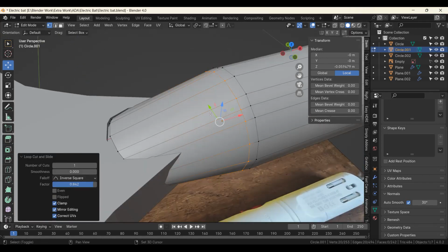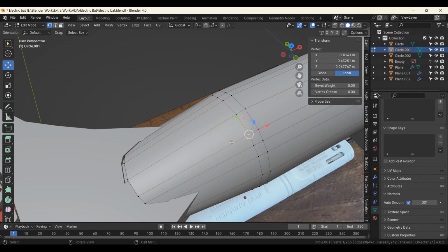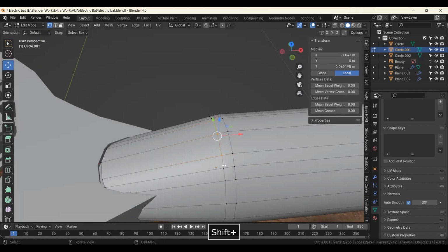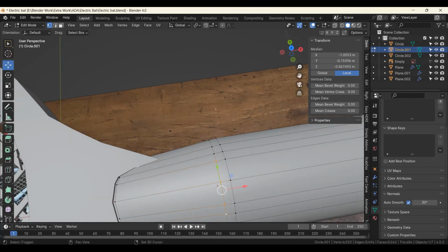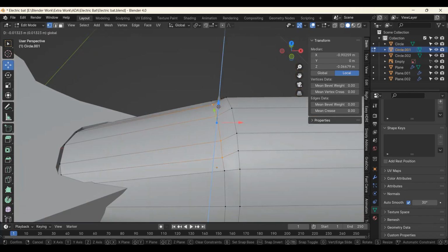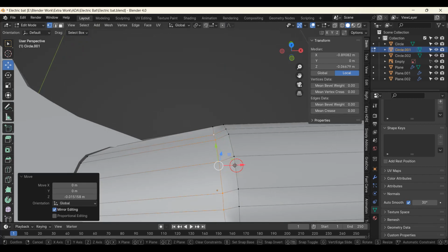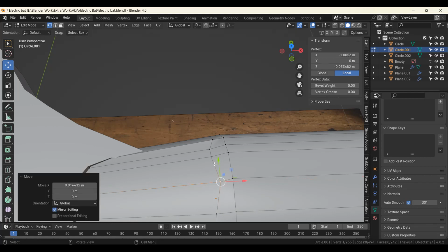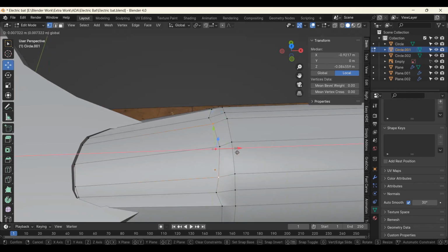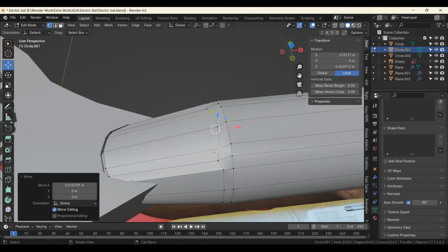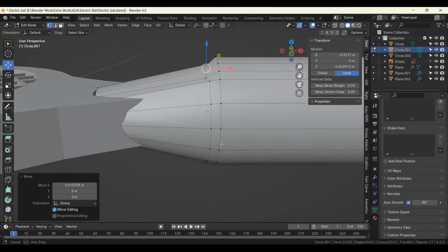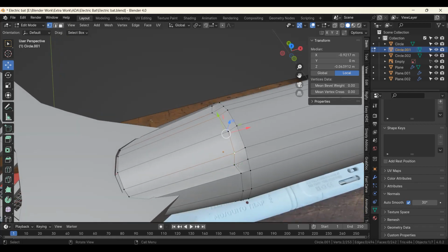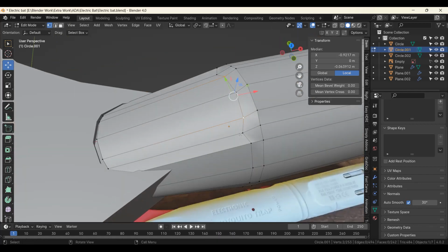Now I would like to adjust this thing, the vertices. I'm just selecting the tools and selecting over here and using the move tool. It is better, but also you can do GX and like this way, or GX or GZ or GY this way. So yeah, I'm just doing it with the move tool.